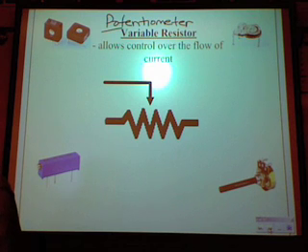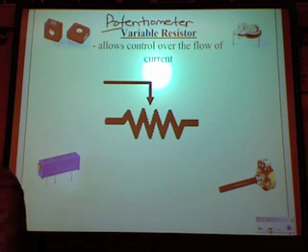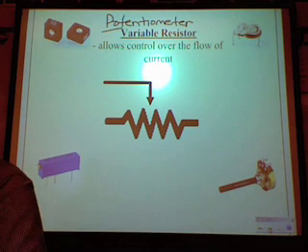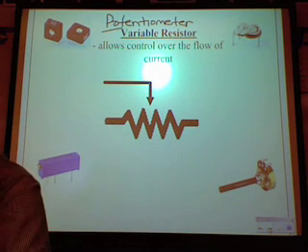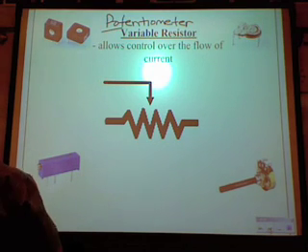How much resistance does this one have? 1 million. Okay? And this one is in code, so you're not going to know by looking at it. You'd have to look up the number. So you can't just go by the size and say, okay, this has more resistance than this one. You have to read off the code. Just like you can't look at these and know based on the size how much resistance. You use the colored bands.